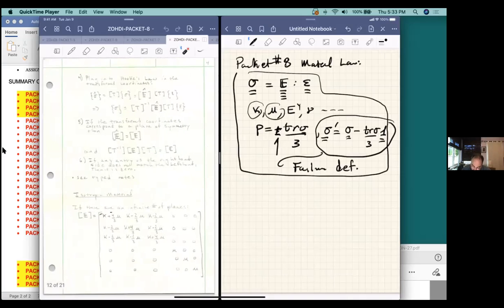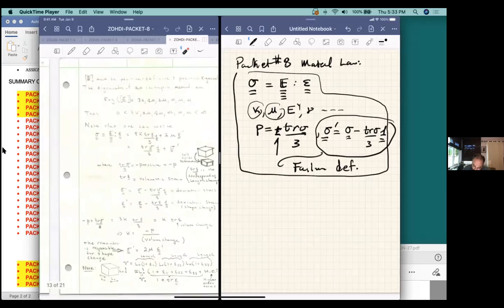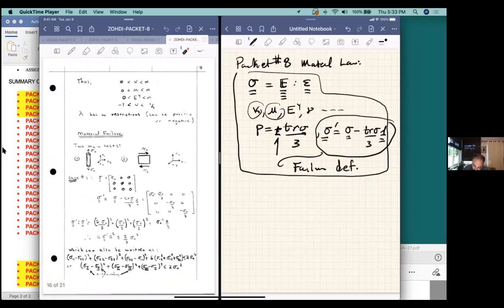You don't have to sweat over the elastic symmetry stuff. We didn't cover that in depth. So you can, of course, ignore that type of analysis in the problem. But for those of you that are in material science in particular, it's also critical, the concepts of material failure and how we actually calibrate material failure on page number 8 of that packet, with basically starting with a simple one-dimensional stress-strain relationship or law, or a shear type of test, how we can construct the von Mises criteria. That thing is, of course, central to almost everything we do in terms of failure analysis.